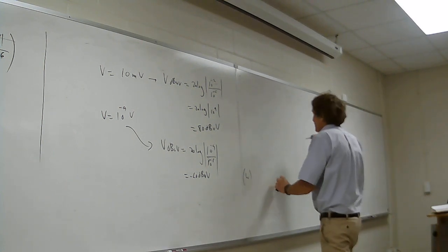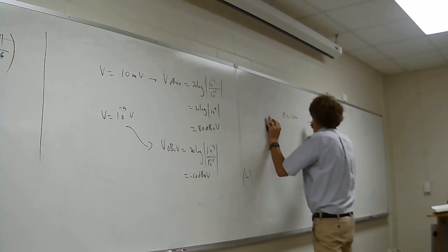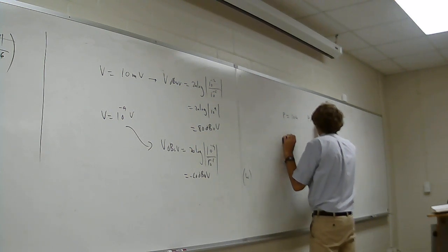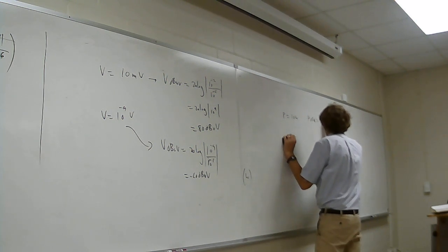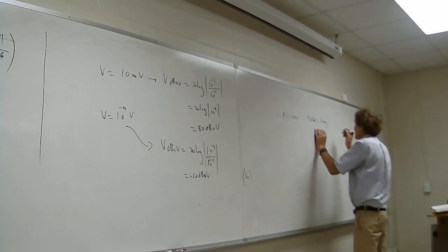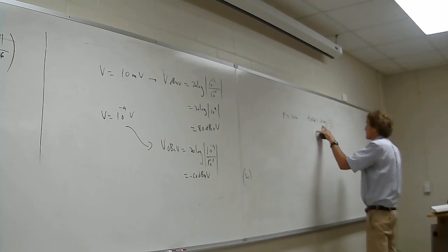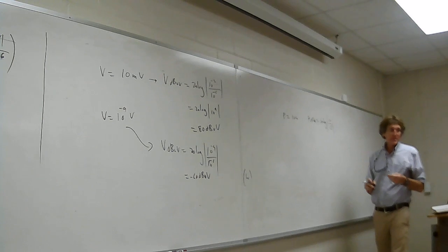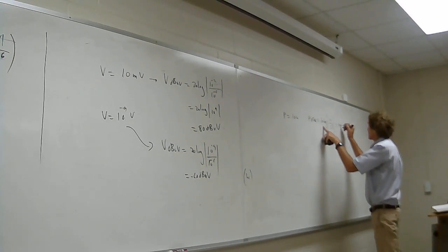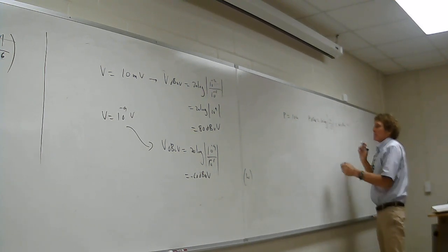So what if we have a power equal to 10 watts? What's that power in dB milliwatts, dBm? It's 10 times the log of the magnitude of 10 over 10 to the minus third. That's 10 to the 4th. What's the log of 10 to the 4th? Log base 10? 4, right? 4 times 10 is 40. So it's 40 dBm. And that would be for 10 watts.